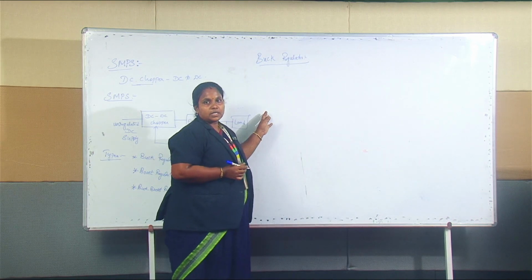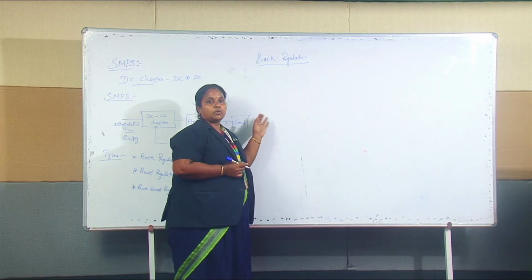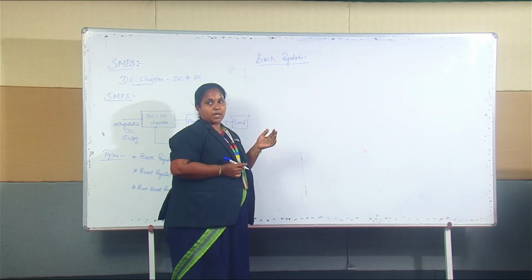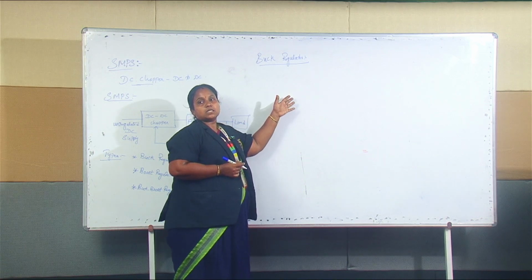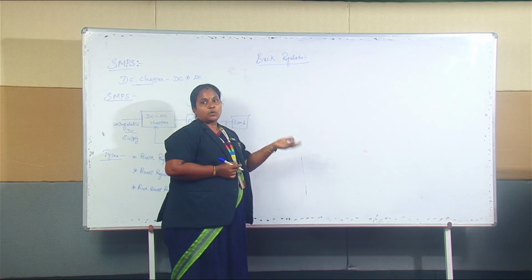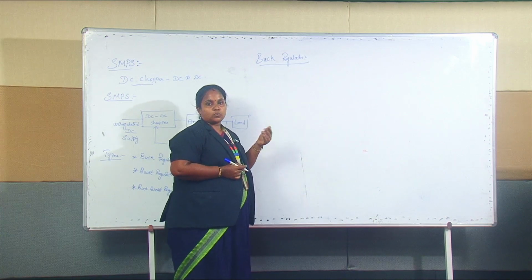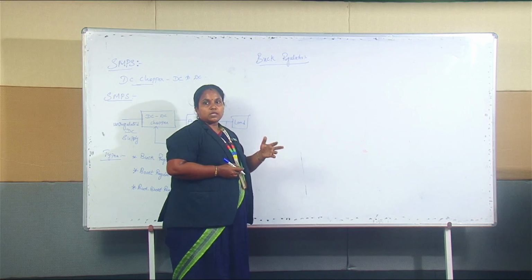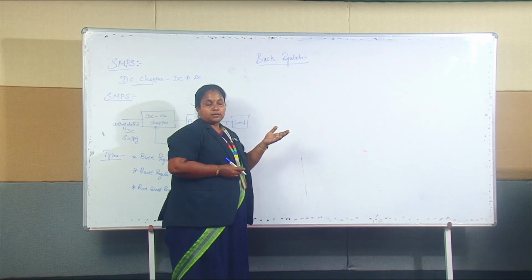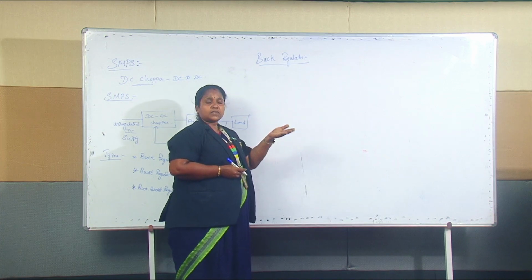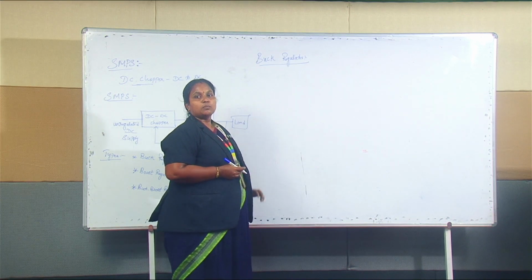It is a kind of step down chopper. As you know, choppers are of two types. One is a step down chopper and the next one is a step up chopper. The step down chopper is used for the conversion of a high level voltage to a low level voltage, whereas the step up chopper is used for a boost operation, which means that the input voltage can be increased to twice or thrice based on its duty cycle ratio, converting it into a higher level voltage in the case of a boost converter.